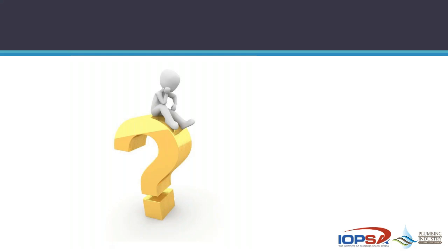And on that same detail, they indicate that you backfill and ram fill properly compacted soil up to the top, and you provide the concrete surround at your finish level. So when you're looking at supporting, there's no problem, or there shouldn't be any hassle.